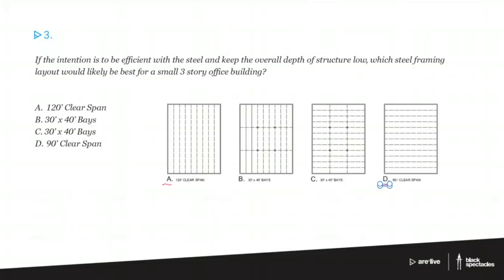They're both 30 by 40 foot bay systems. And 30 by 40 foot is very specific because the sweet spot for steel is going to be right in that range. Classic steel spans are 30, 35 feet, 40, 45 feet, right there. Maybe down to 25 might still be pretty efficient, possibly up to 45. You can span all sorts of distances in steel.